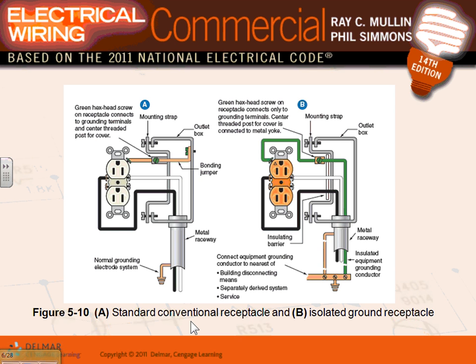So what do you do? You take a number 12, or number 14 in this case, isolated ground conductor all the way back to the service panel. Normally we don't do that. You take it to the panel. If this panel has an isolated ground system, you bring it all the way to this bar, which is completely isolated from the box, and from this bar you take another isolated ground conductor all the way to the main, and you land it on the main equivalent grounded conductor bar.